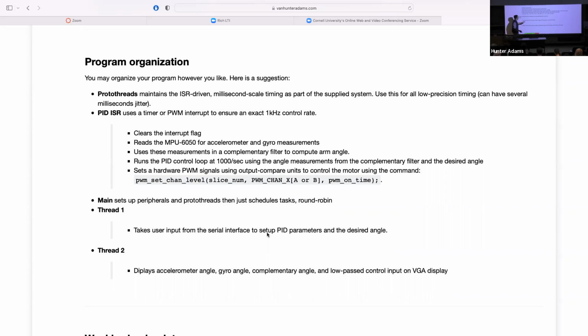And so for that reason, in lab 1, we did not see in the code an interrupt service routine tied to a low-level interrupt. This demo code is set up such that there is an interrupt service routine tied to one of those 26 interrupts that both cores see. In particular, it's one of the interrupts attached to the PWM hardware peripheral, just so that you see how that's done. Right? I just wanted to give you some demo code that showed how you tie an interrupt service routine to a lower level interrupt without the SDK levels of abstraction in between.